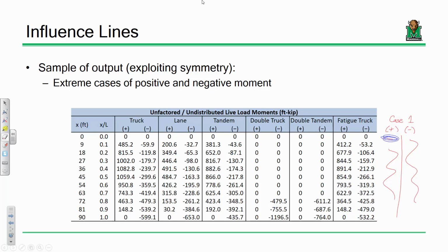But if you've got a bridge that's got significant horizontal curvature, significant skew, and additional geometric complexities, it's time to break out the full-blown 3D finite element software and do it for real. Like three-dimensional moment and shear analysis. This is simplified because, you gotta understand, most bridges that bridge engineers design are somewhat simplified. When you've got the really complex bridge, you gotta do the really complex analysis. You have to.